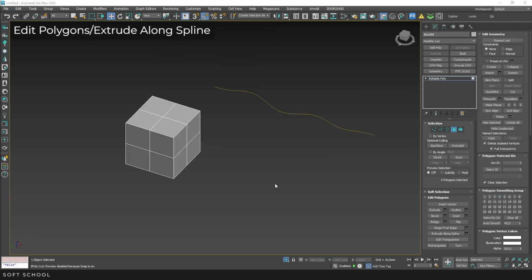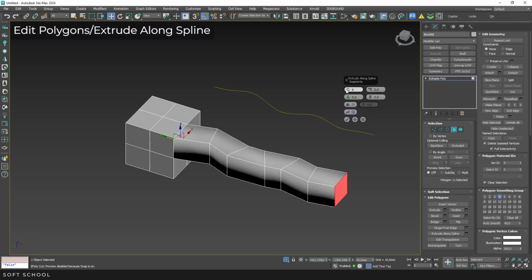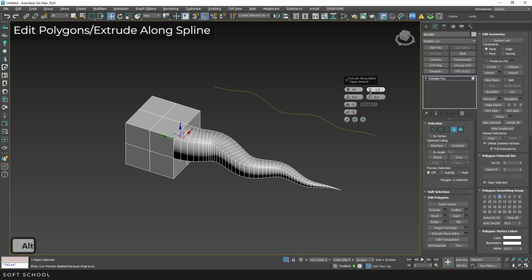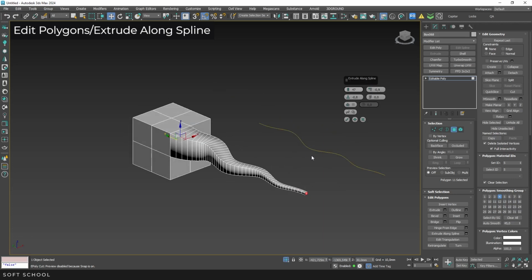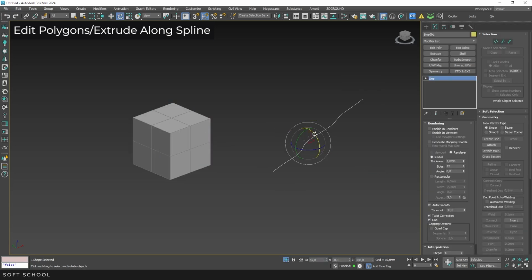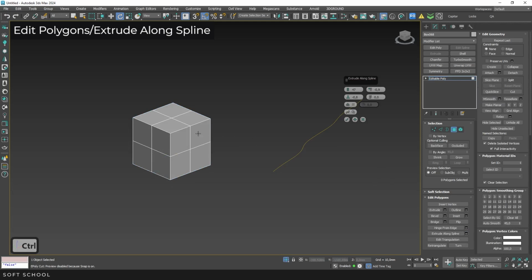The Extrude Along Spline tool requires a spline. Activate the Settings menu. Choose the spline and polygon. Set segment count, adjust expansion or contraction, and adjust the cone curve. Extrusion follows the spline direction. If the checkbox is enabled, extrusion follows the polygon normal. You can also set twisting and spline flipping. In spline extrusion, adjacent group settings are not available, so adjacent polygon normals always sum.